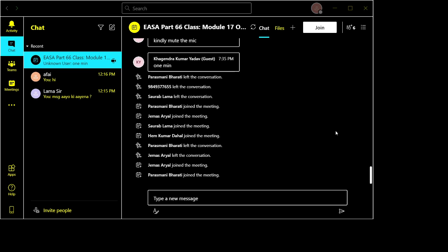problems. So if you suspect your engine's not as healthy as it was, you check the figures with the engine logbook, you check your actual running figures in the cockpit, and then compare, and there should be a slight discrepancy, and hopefully within tolerance. Obviously, engines will wear out, like everything else, getting older, just like myself, and you need to be refurbished. Okay, be allowed up to a certain amount of discrepancy.